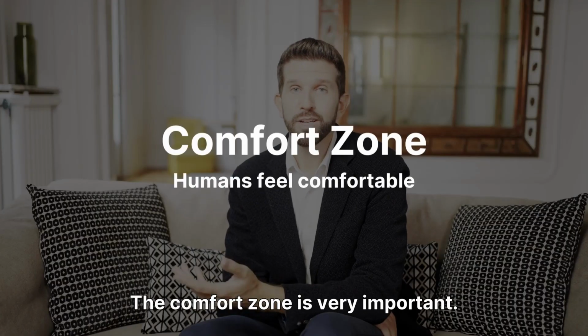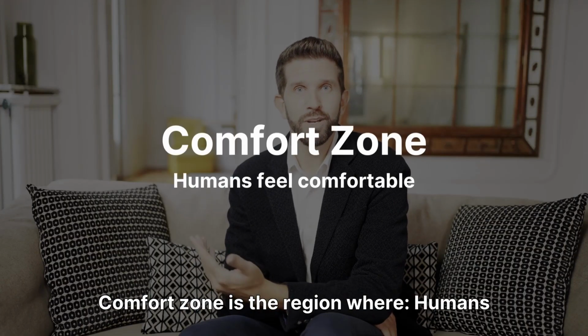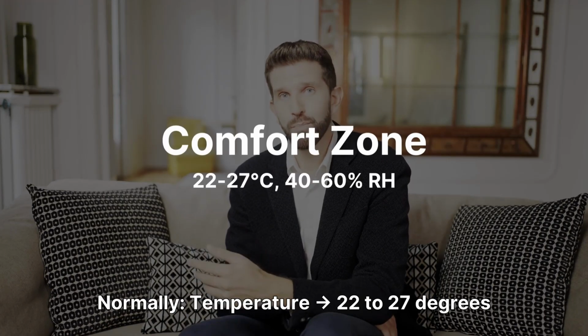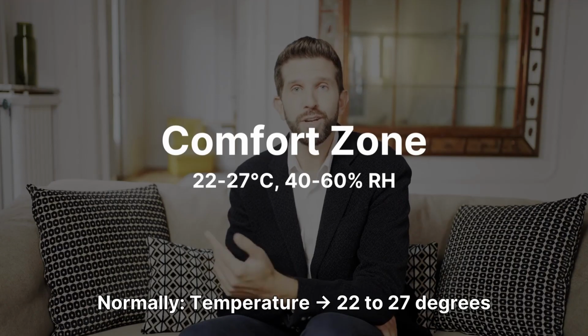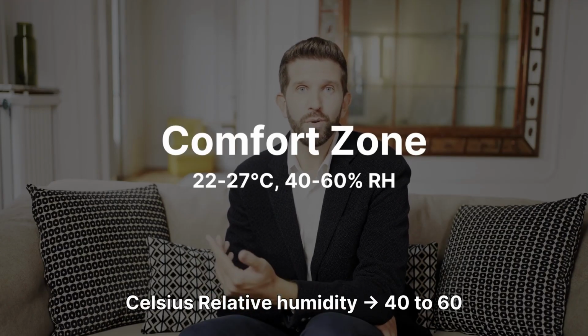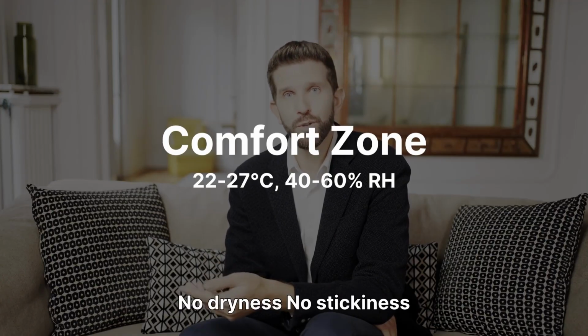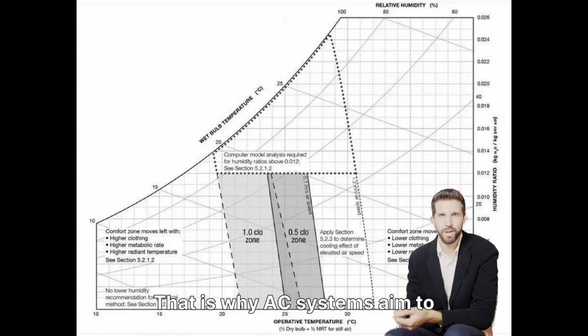The comfort zone is very important. The comfort zone is the region where humans feel comfortable. Normally, in this zone, temperature is 22 to 27 degrees Celsius and relative humidity is 40 to 60%. Sweating works properly, with no dryness and no stickiness. That is why AC systems aim to keep air in this zone.